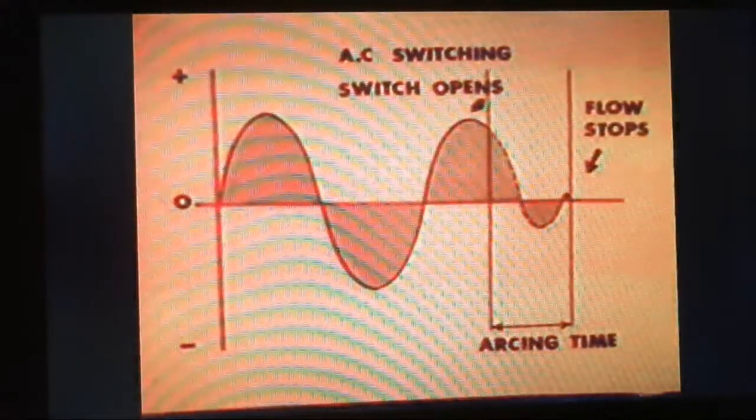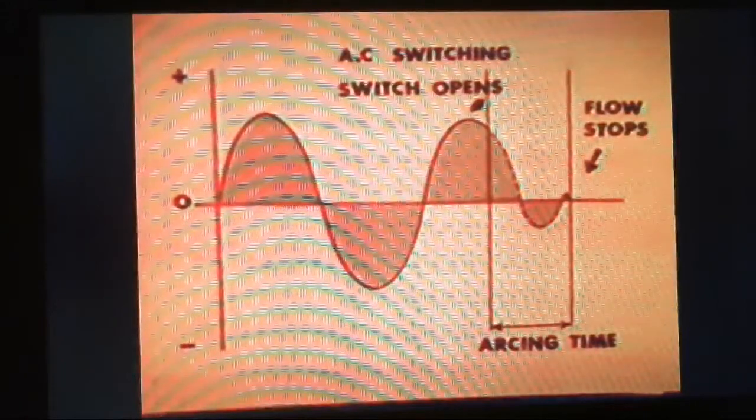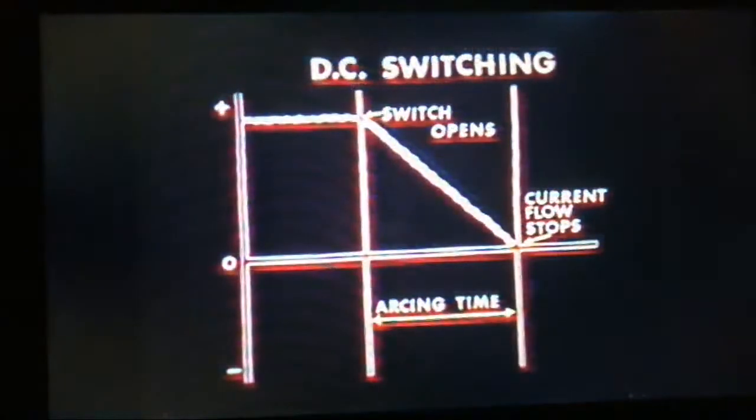Even without the effects of induction, DC voltage is harder to interrupt than AC, which will extinguish itself rapidly when the zero voltage is reached. But with DC, a high enough resistance to stop current flow completely must be developed. The arcing time is considerably longer, and during this time, current crosses the open switch in an arc effect and must be quenched as rapidly as possible.